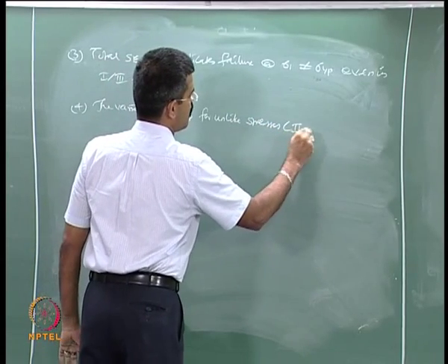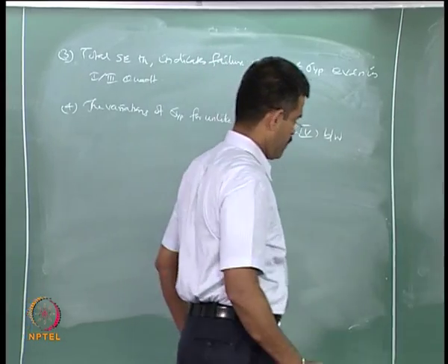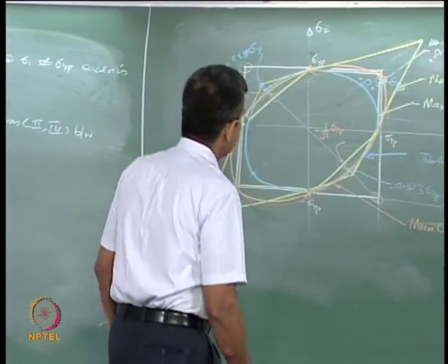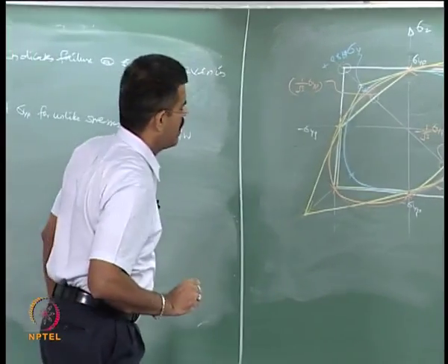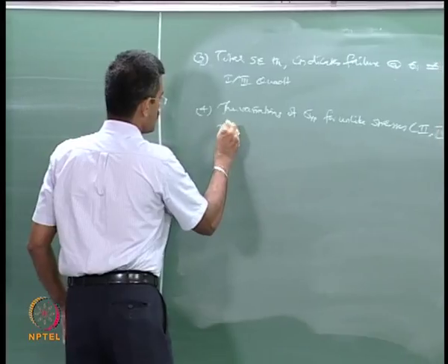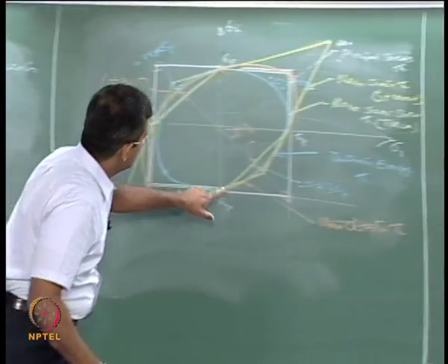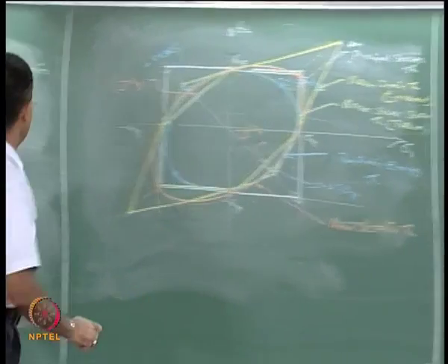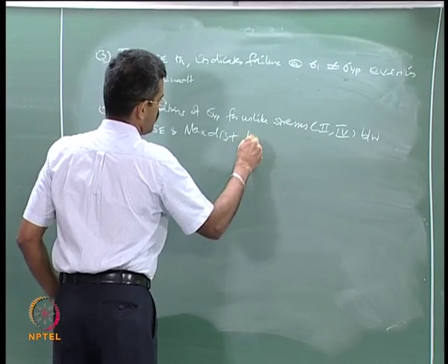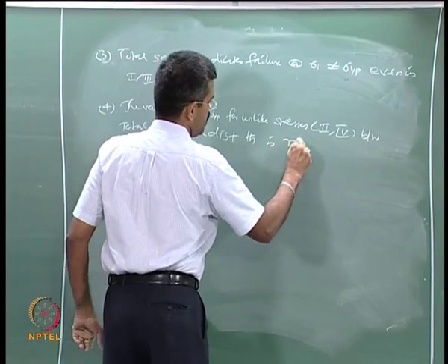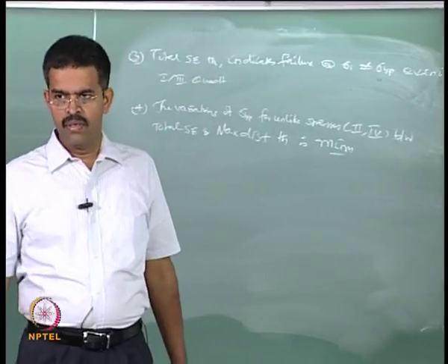So I am focusing on quadrants 2 and 4, between the total strain energy theory, the blue one, and the orange one, the maximum distortion theory. The difference is minimum, they closely agree. What does it mean?